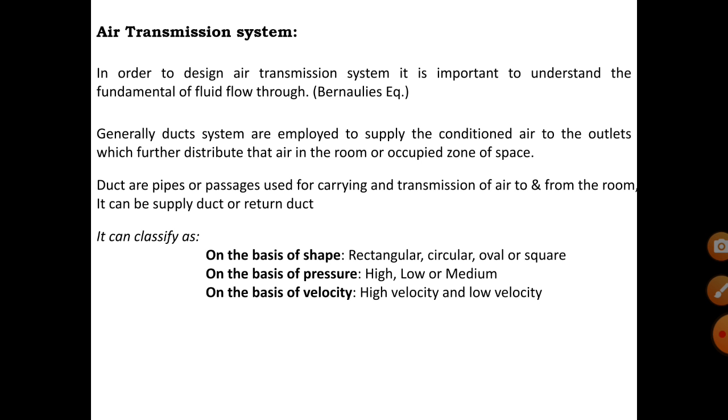Regarding insulation, I'll tell you one thing, that is the discoloration of the wall. There is one phenomenon you might have seen in different buildings: wherever there is an arrangement of different types of ducts, you can see that the color of the wall has somewhat disappeared. It is because of sweating of the duct.